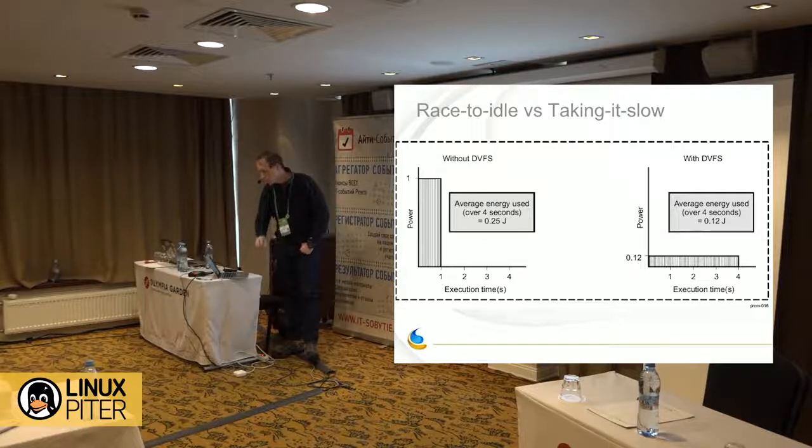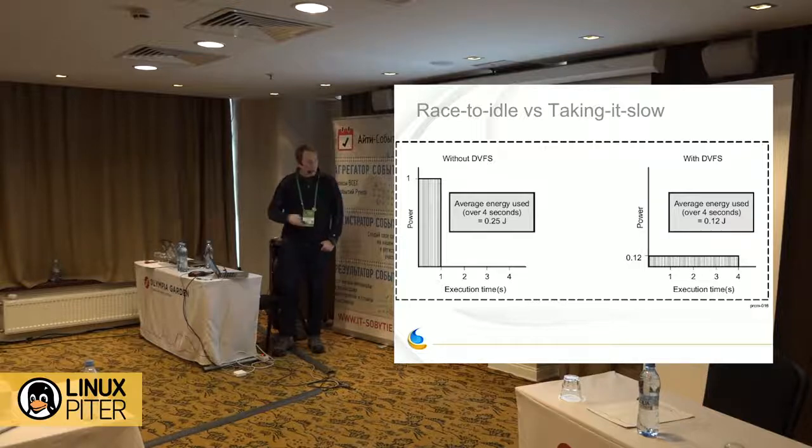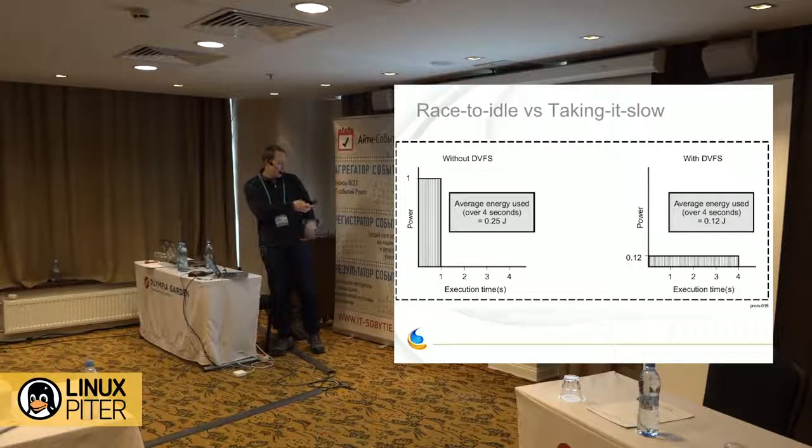All right, so this is our first look at an actual power management policy. I'll use my laser pointer. On the left, we have what I call a race to idle philosophy. The idea is to run as fast as possible and get the work done very quickly and spend more time in a deep idle state.